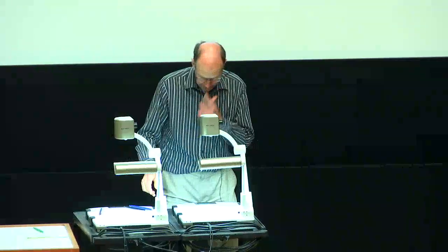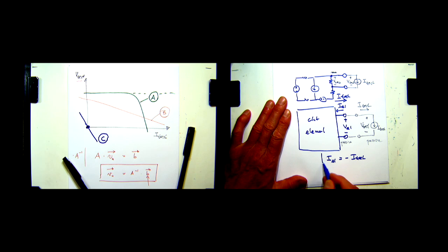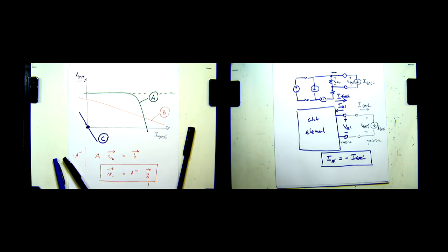So the way we fix this is simply to realize that these currents are not the same, but closely related. One of them is the negative of the other one. But if we wanted to figure out, for example, the power dissipated by the blue box or by the test source, then we would have to make sure that we are in passive sign convention. Otherwise, we get the wrong sign. Okay? Does this make sense? So look at that a little bit more. It's important not to get confused. Incidentally, that's kind of a bonus question. I could also have, if I had measured something like this in that particular circuit, D.